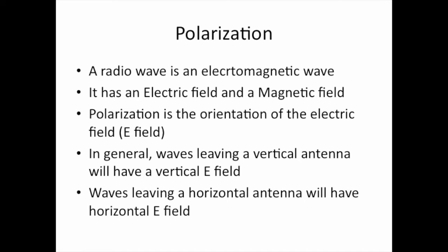At VHF, when you're transmitting vertical to vertical, then it's important, because your vertical wave at VHF is probably going to remain more or less vertical for line of sight communications. But once you throw the ionosphere into the equation, then everything changes.